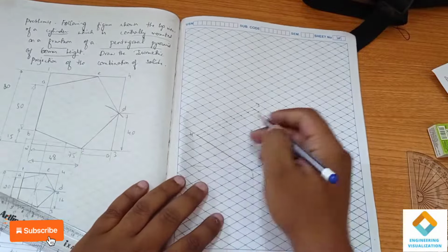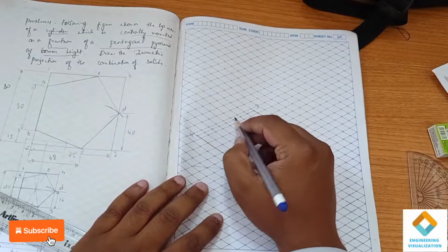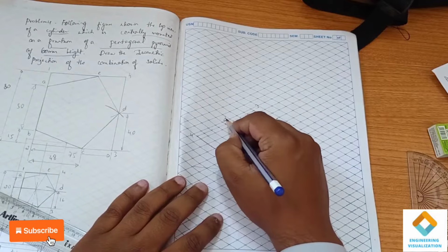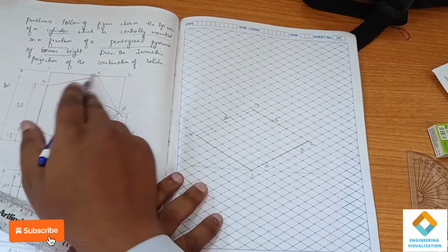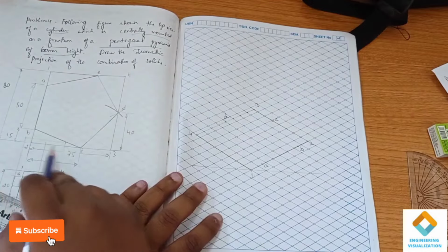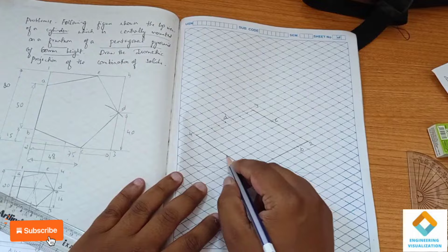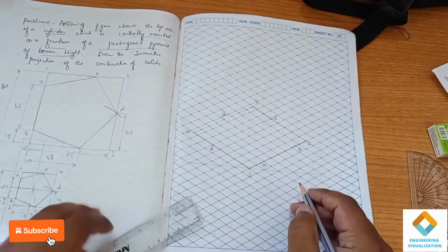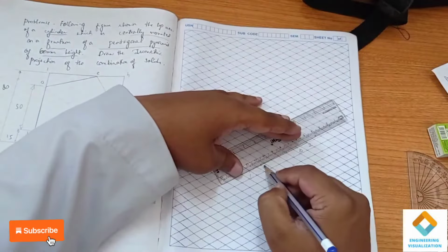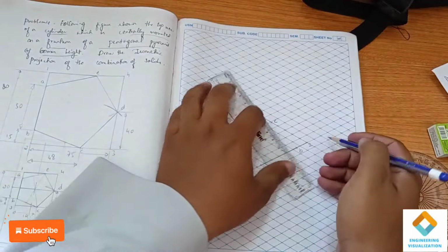Now from 3 to D it is 40. 40 means 4 boxes. 1, 2, 3, 4. It is D. Now again from 4 to E, so I can take 1E. 1E it is exactly equal to 2C. That is 48. 1, 2, 3, 4. 48 means it here. That will be E. Now we are going to join these points to construct the pentagon.